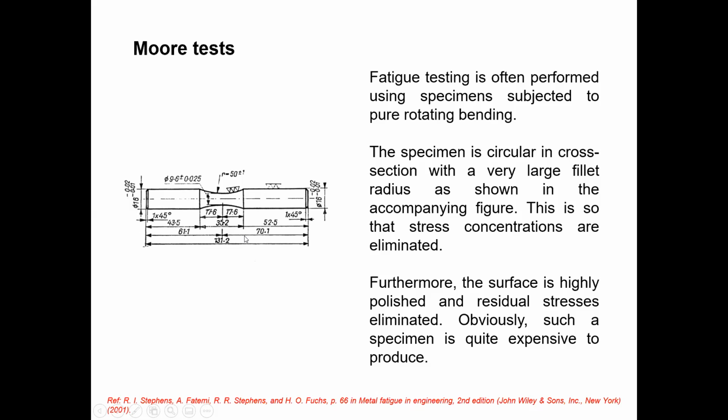I hope you understand why they put the large fillet here: to reduce the stress concentration. Still, you don't know what stress concentration is, but you know that if there is a sharp edge, there is a high probability of breaking the material at that point. That is the meaning of stress concentration. You will learn about that later. To reduce the stress concentration, you can put a very large fillet, then the stress concentration will be distributed, so it will be delayed.